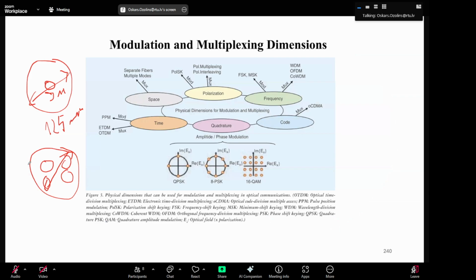Here, you can still keep the same size, 125 microns, but add more cores. So basically I have four independent fibers here, which means that your cable capacity is multiplied by a factor of 2 or 4, and that's a big gain if you are laying down transoceanic cables. You expect to deliver capacity, and capacity means money. So then you can factor 2 your income from that cable.